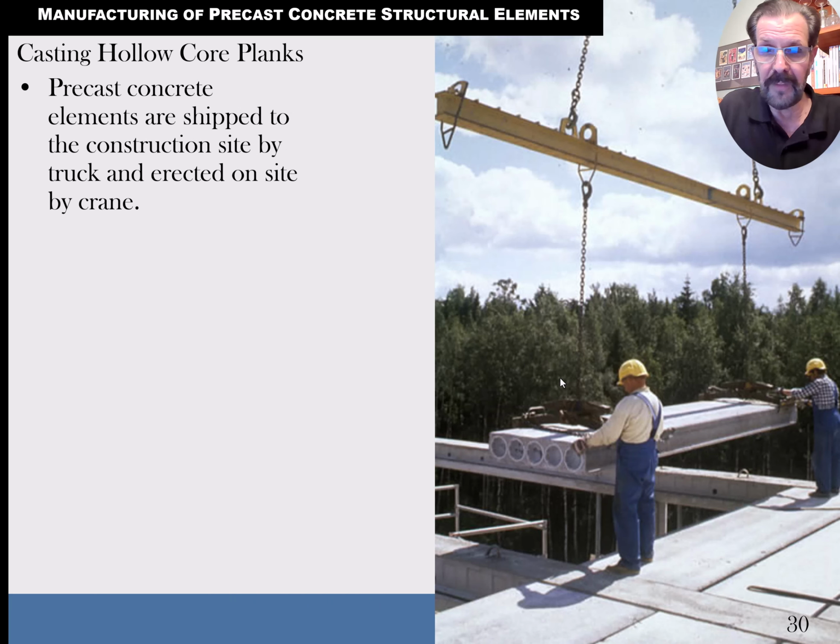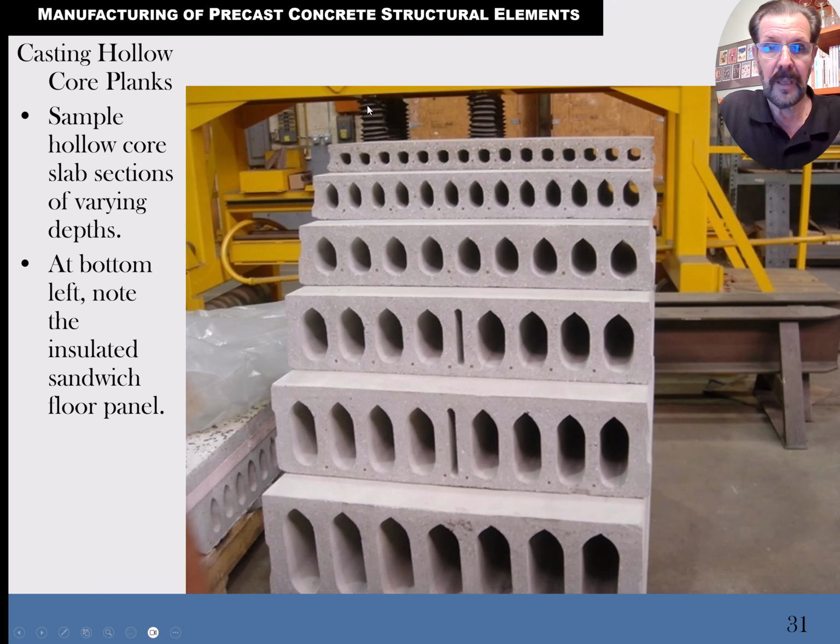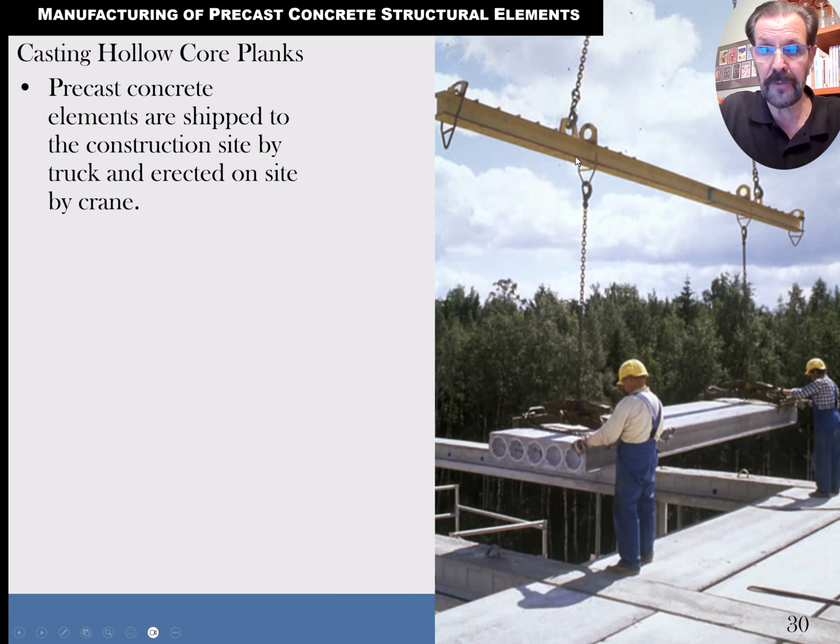Here I can't see enough definition in the picture to tell what they're using to lift. It may still be grabbing it by the keyway, but maybe this particular design has the top keyway a little further back or something. I don't quite know. Okay. And it's very common to use spreader bars in pre-stressed concrete to pick up these girders, so you have more control. And it can be much, much longer than this for a big long girder and a much heavier spreader bar.